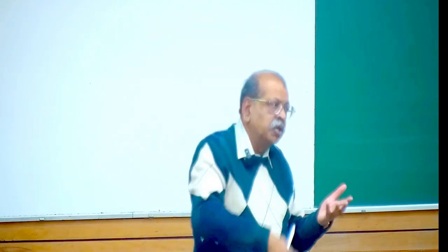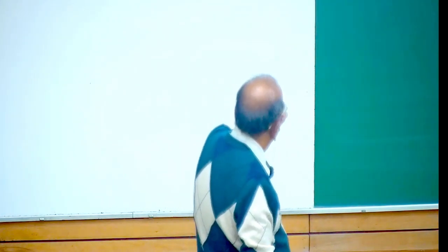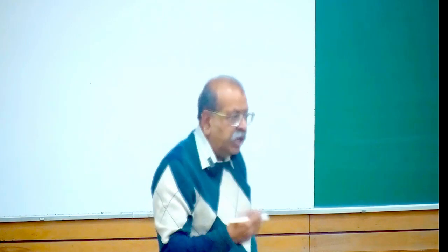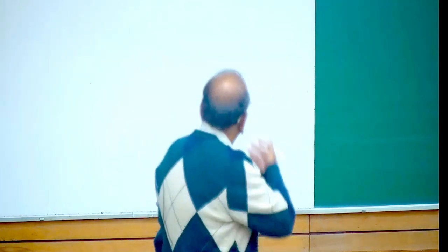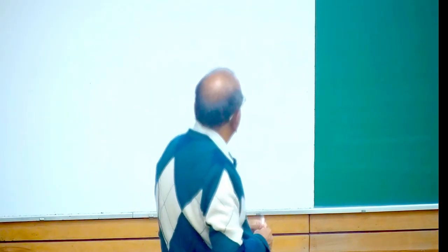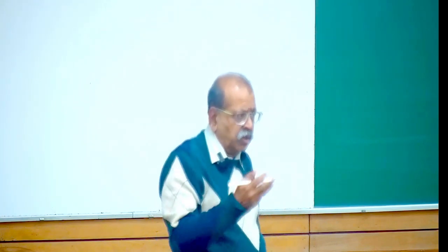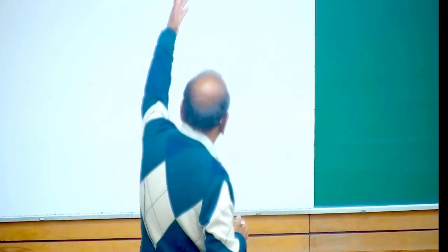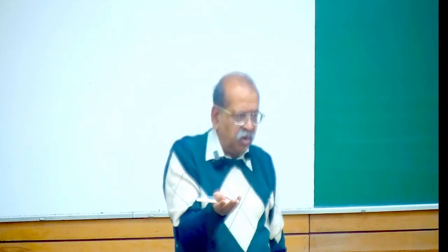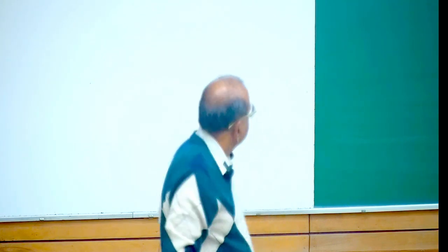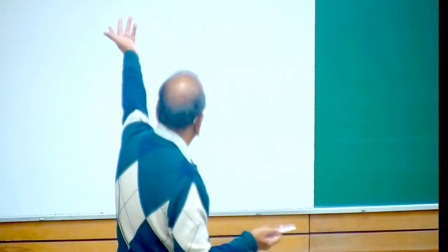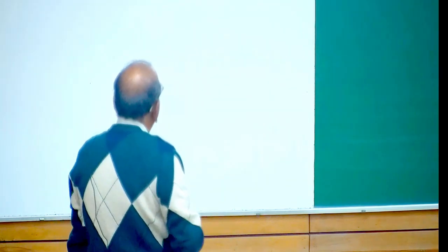You can use either the formula we have done or moment is 0. So you use this, you get the bending moment. And then this is equal to EI d2y/dx2. So we work out, and when we integrate this, two constants will come, because it's d2y/dx squared. To do this part, at x is equal to 0, we have y is equal to 0, and at x is equal to 0, the slope is 0. So you get the values of C1 and C2 from there, and that gives you the elastic curve for AB, which is straightforward.